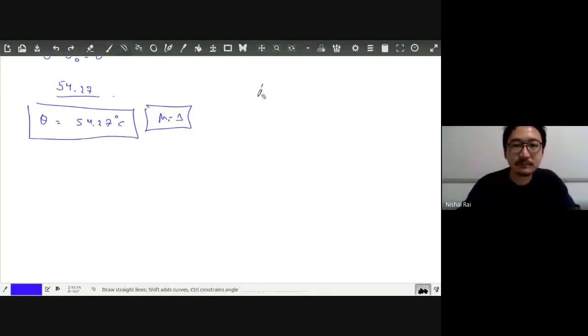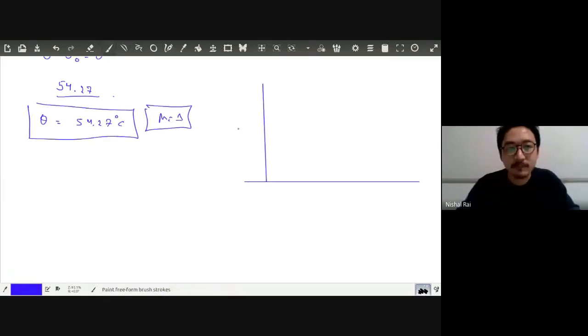This is how you find that the temperature in the rectilinear flow changes over position. As we can see, the temperature theta over position changed in a kind of exponential manner. Initially the temperature was maximum over here, which was 60 degrees Celsius, and it keeps on decreasing.